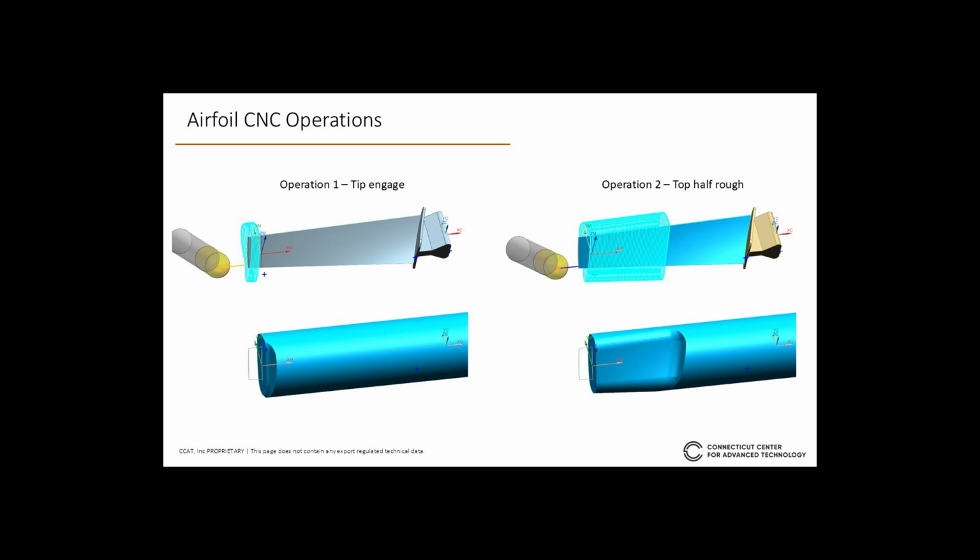The way this is machined, the stock material is put into a three-jaw chuck on the machine, held in a horizontal fashion, so it's rotated about a horizontal axis. The machine tool comes down in the Z direction. Normally you would have the tip constrained, so that as you're rotating the part, you would perform the machining with both the tip and the base constrained.